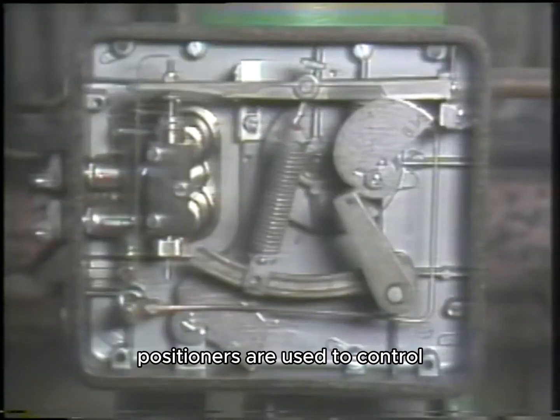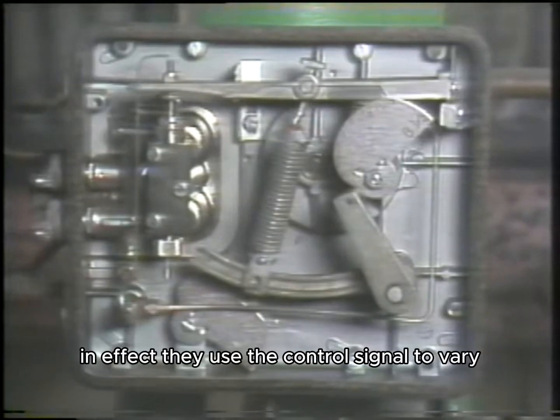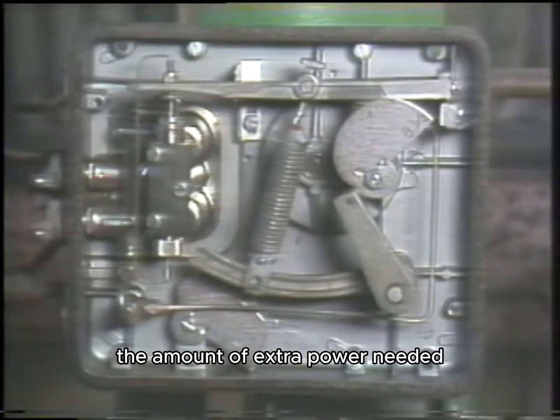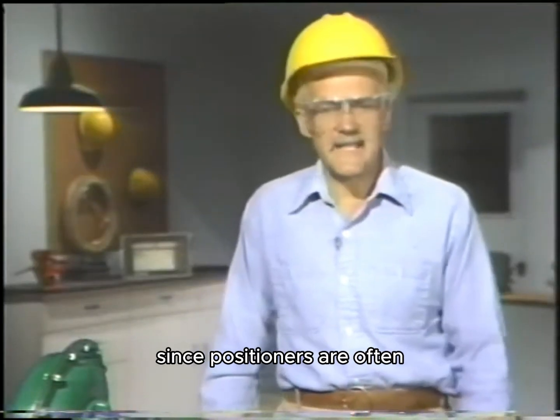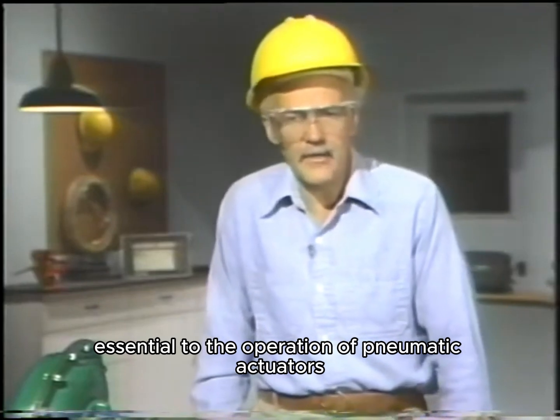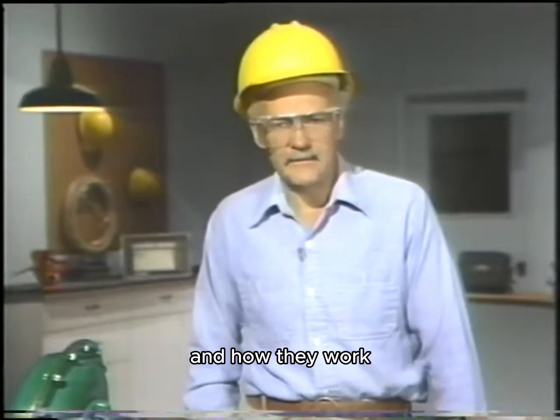Positioners are used to control the extra power needed by many pneumatic actuators. In effect, they use the control signal to vary the amount of extra power needed to overcome mechanical resistance. Since positioners are often essential to the operation of pneumatic actuators, we'll be taking a closer look at how they're built and how they work.